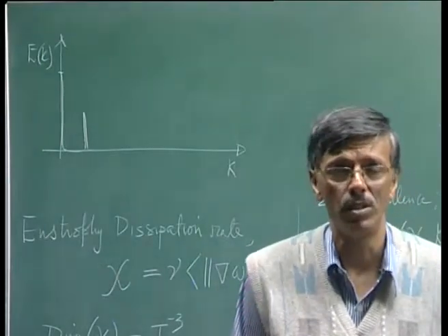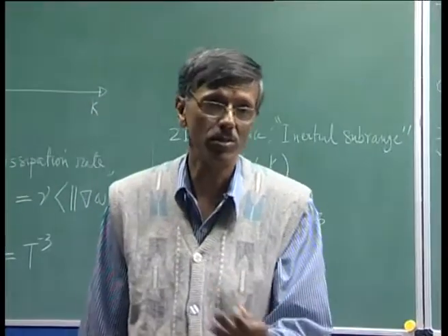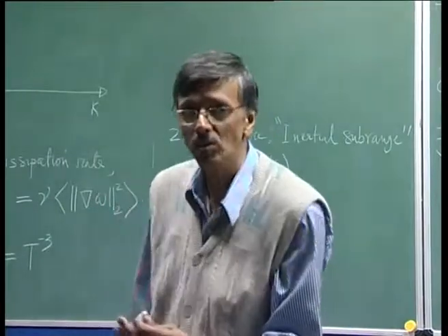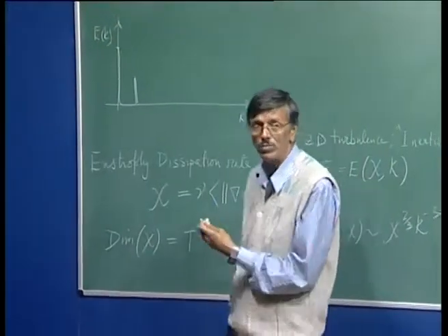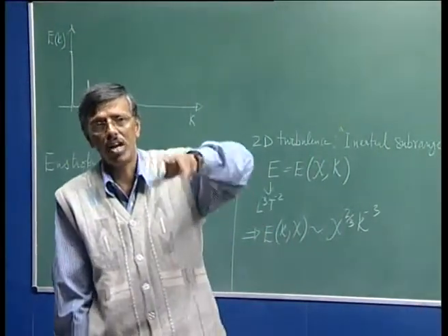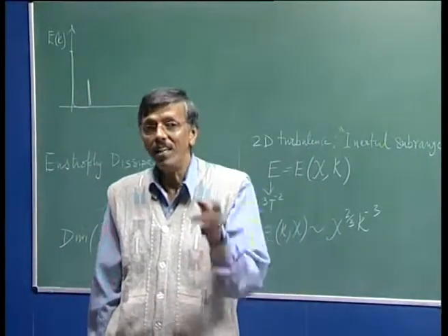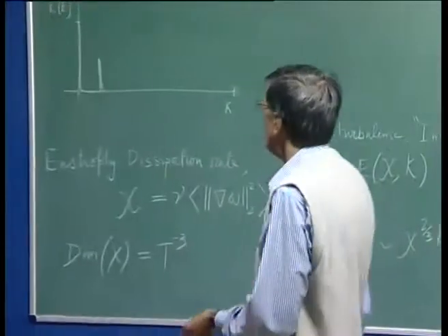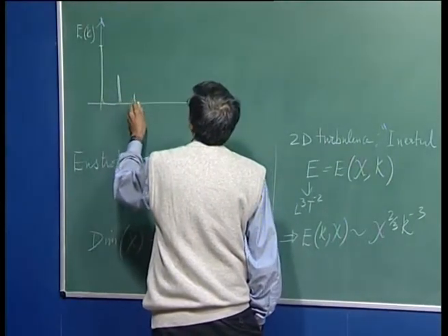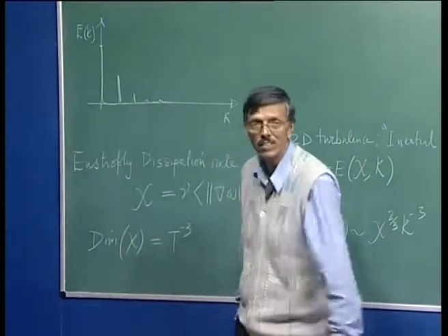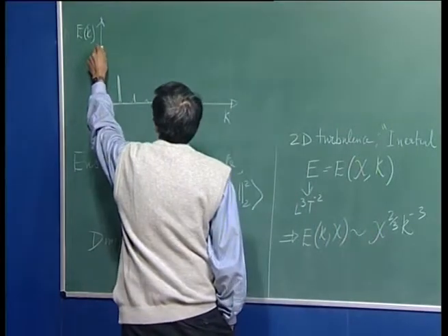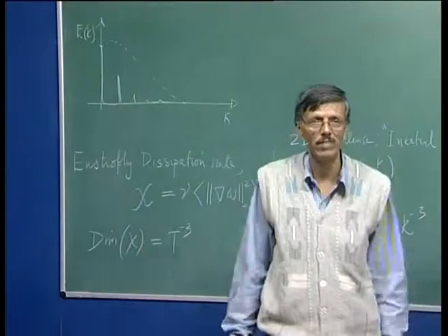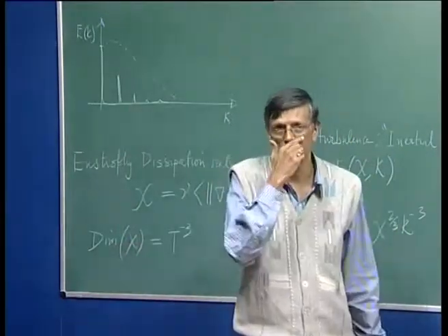And of course, it is a nonlinear dynamical system. So, if I excite the system and it is susceptible to that frequency, it will also be susceptible to its superharmonic and subharmonic. If you take a cylinder and do rotary oscillation, you can really see the presence of various sub and superharmonics. Whereas, if you look at turbulent flow, we have seen that it is a wideband phenomenon. So, energy resides over a large range of scales. Do you have any questions?